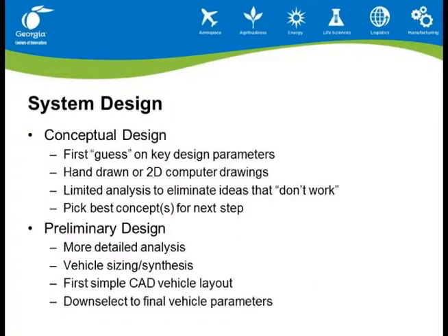Really, the first two areas you're going to be looking at is conceptual design. Conceptual design is really your first guess. You're just looking at where do you want to start with some of the key design parameters. And this is just hand-drawn or 2D computer drawings. You're not starting all the 3D CAD work at this point. This is very quick. You're just getting a lot of ideas out on the table. Limited analysis to eliminate some ideas that just don't work. And then you pick the best ideas, the best concepts that you looked at to take to the next step,